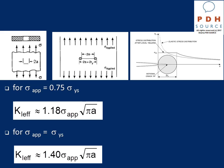Now, if we plug the ratio of the applied stress to the yield stress, 0.75, in the previous equation, and this is basically a reasonable upper limit to the applied nominal stresses in a structure, we can get an 18% increase.